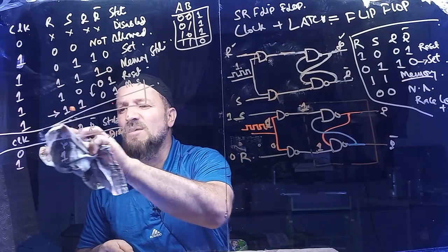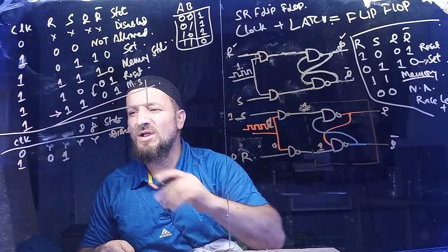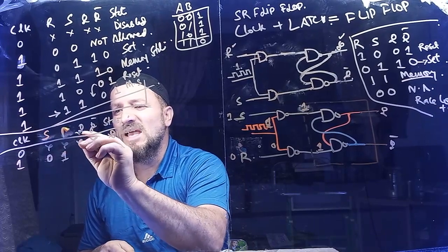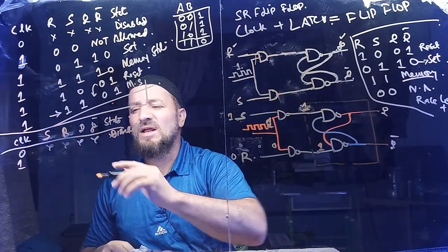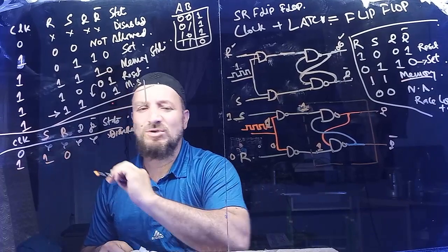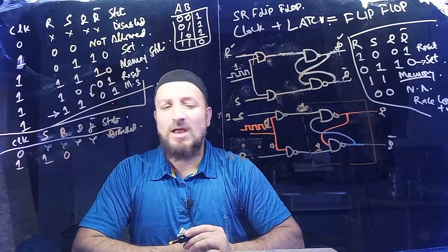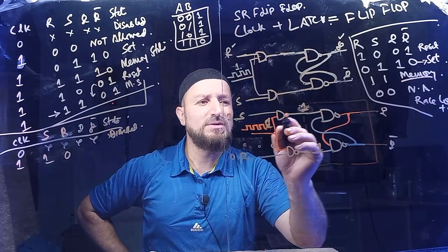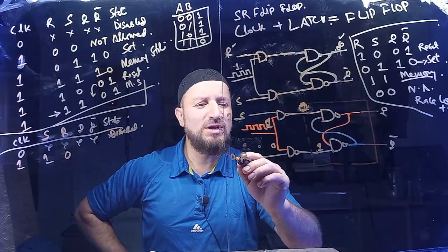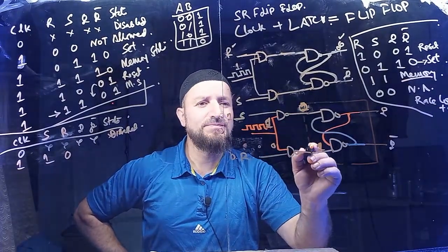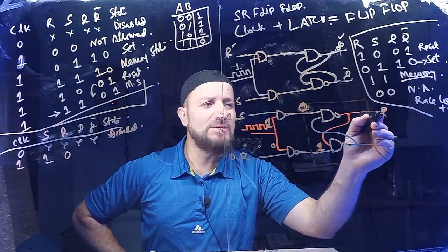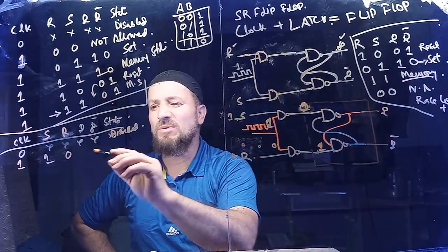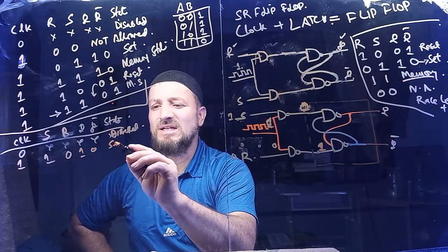We want to see what values come where. But now it makes proper sense, because S first and R after. Now I am putting S as 1 and R as 0. We know when S is 1, it will flip it and make it 0. It is 0, it will flip it and make it 1. So the bottom side is 1, it's going to set. That means Q will be 1 and Q complement will be 0. So it is a set state.